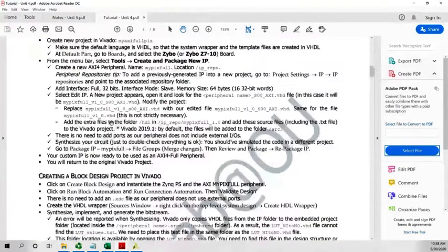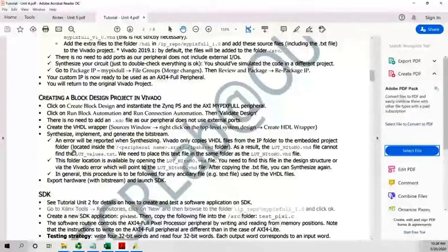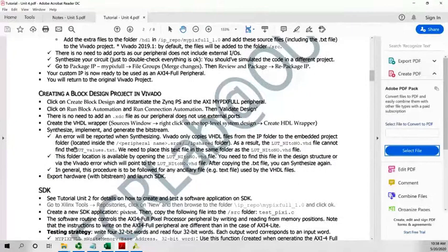Remember that there was a problem with the text file. That's a very annoying problem. I mean, I started doing this a long time ago, and even up to now, they have not fixed this issue. I have not found a better way to fix this issue. I had to do it manually. Now you might be wondering, why do I have a text file? Well, because I'm using a LUT based project, so I read data from the LUT to implement my circuit. You will find that in many cases you might need to read from a LUT text file.